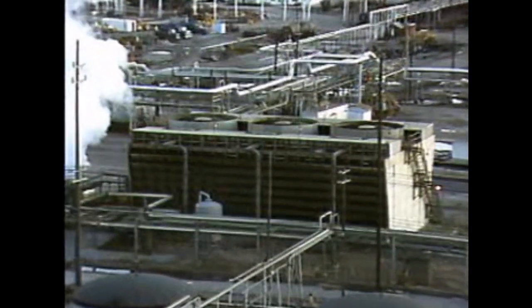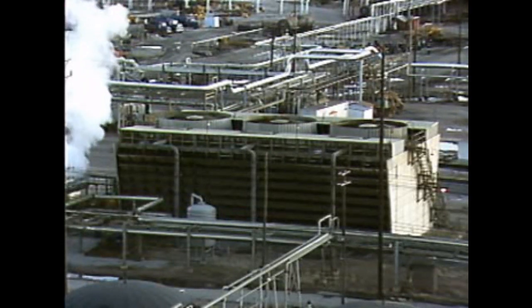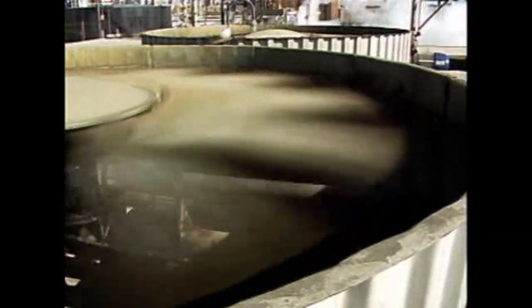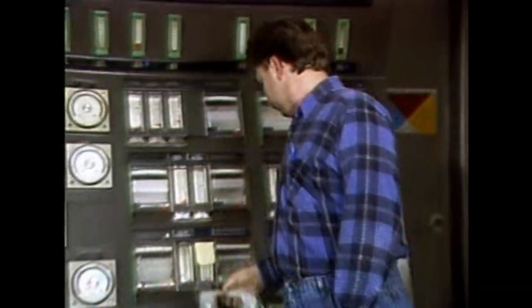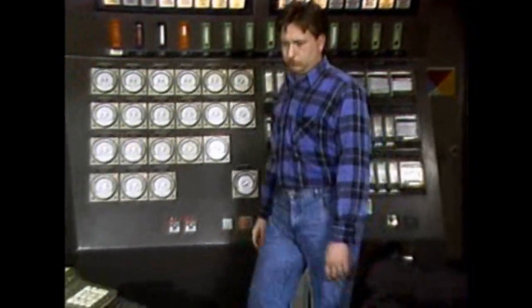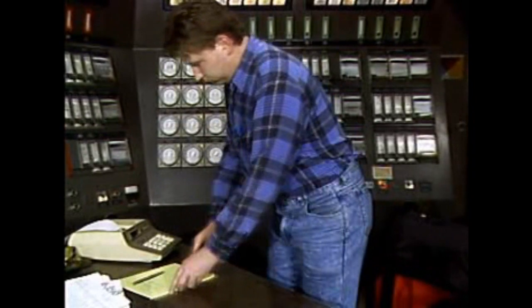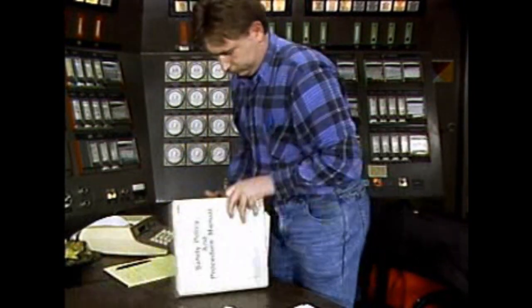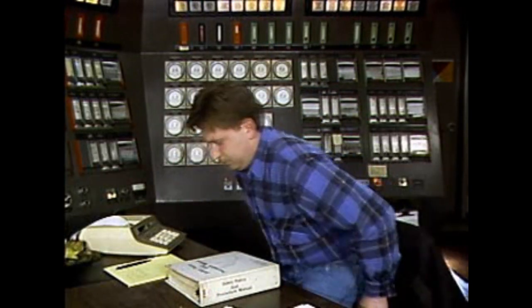The next step is to determine what actions or adjustments are needed to correct the situation. In this case, the second fan in the cooling tower can be operated until the problem in the production process is corrected. Before making any adjustments, the operator needs to evaluate the impact of the corrective action. He should check process instrumentation and facility procedures to make sure that any actions taken will be the proper ones.